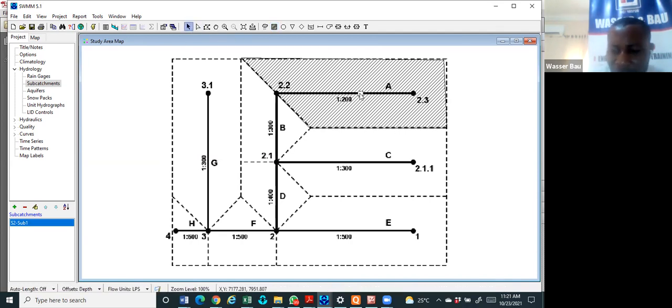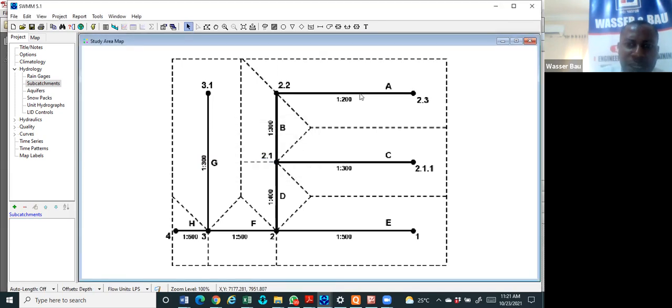But before I do that, there's something I forgot to tell you. So I'll click on it again. I'll click delete. I'll delete it. When you open any software for detailing, the first thing you always do is to set your preferences. Go to options, go to your view, set the preferences, how you want your display to be.